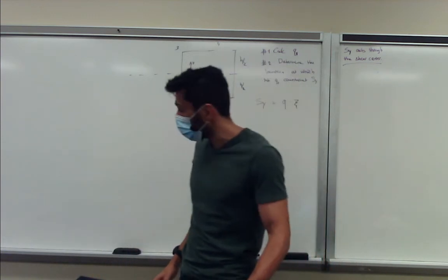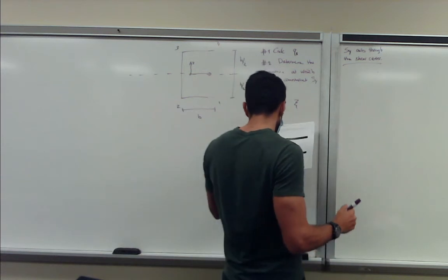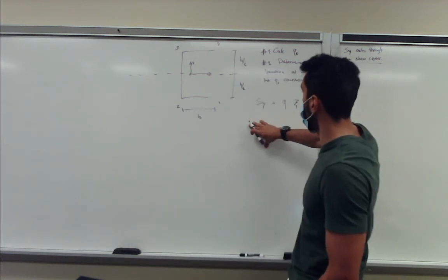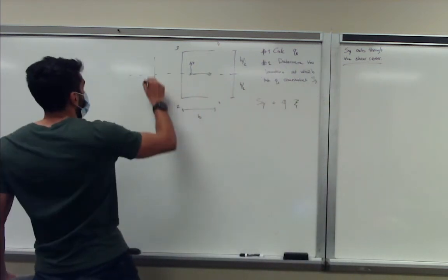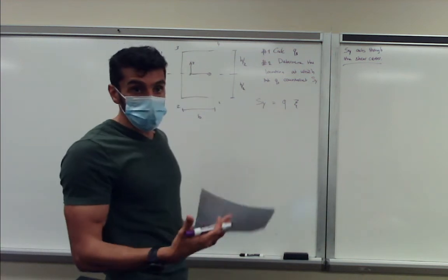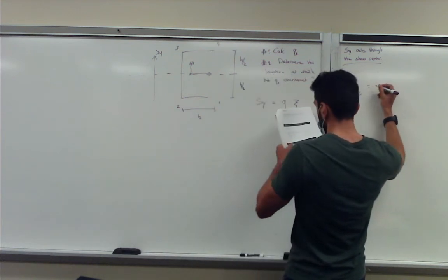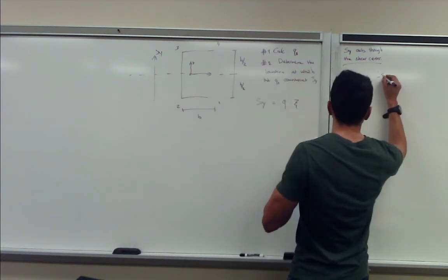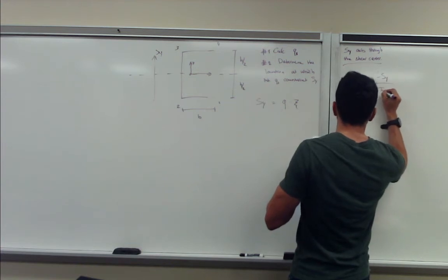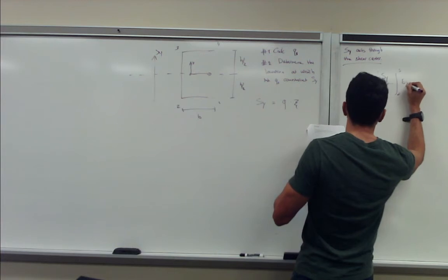So let's do this problem very quickly. We know there's only a shear force applied somewhere. Let's call it here, Sy, right? It's symmetric. We have no Sx given, so we can reduce our shear flow equation to a simple form of negative Sy over Ixx, the integral from 0 to s of t y ds.